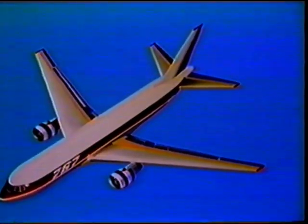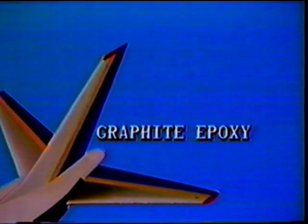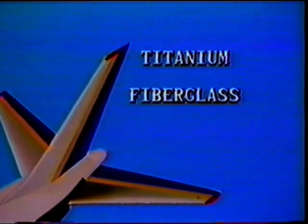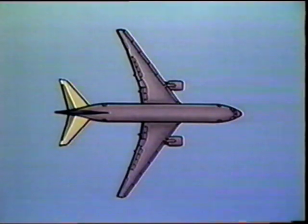New lightweight materials are used extensively in the manufacture of the 767 flight control surfaces and associated hardware. Graphite epoxy materials have been incorporated into the flight control surfaces. Titanium, fiberglass, and advanced aluminum alloys are used in the supporting structures. Each of the control surfaces will be shown, beginning with the horizontal stabilizer.